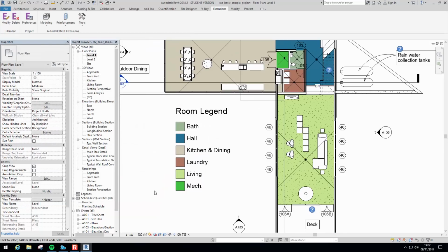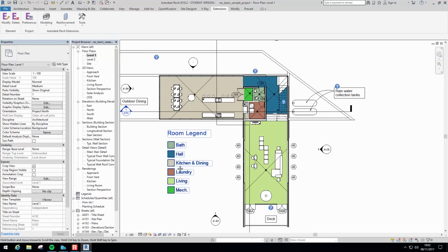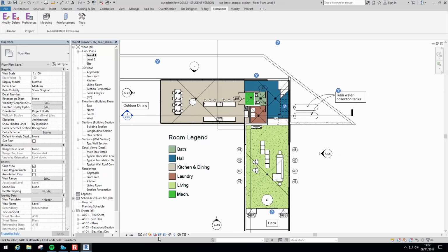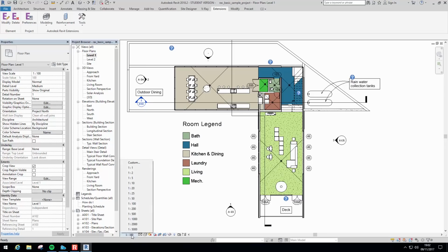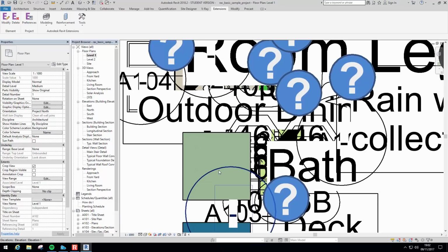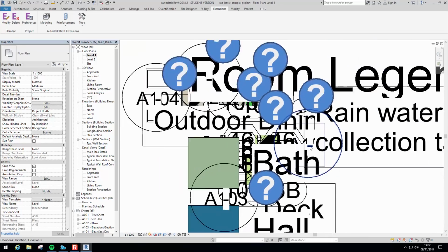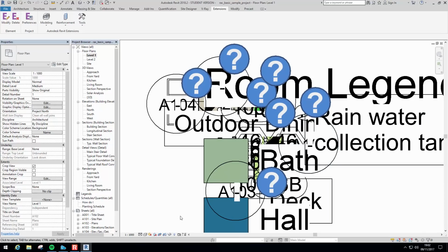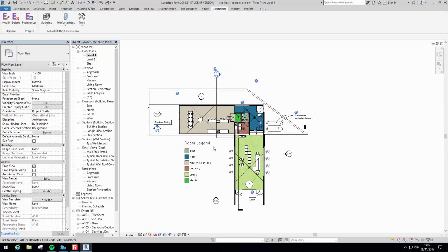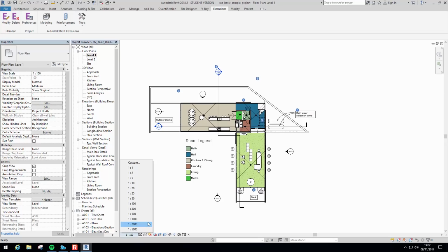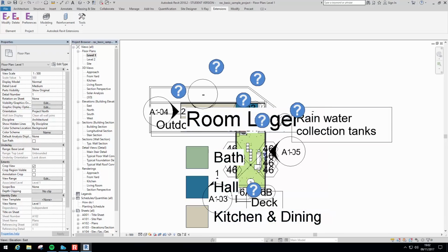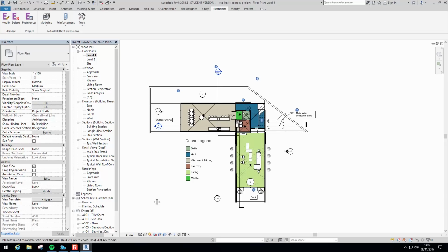At the bottom here, similar to visibility graphics, this is applicable to all the views, you have the display functions. The first one is changing the scale, so you can change the scale to 1000, for example. That's just an extreme, and as you can see, the text is scaled in accordance with the scale at the bottom. So if you leave it at 100, it scales correctly, but if you're doing a master plan, for example, at 1 to 500, you wouldn't have those texts, so those will be switched off. If I go back to 1 to 100.